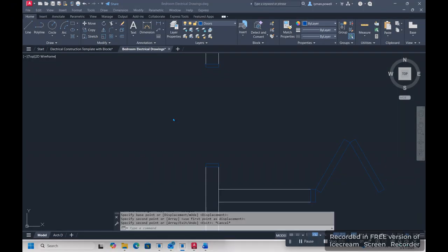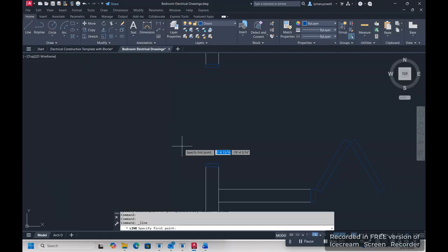So we're going to make us a right-hand door. That means the hinges will be on the right side as you're looking at it to go in. And we're just going to do a line from here, and this should be again a 30-inch door. So we're going to draw a line 30 inches, and you can just type in 30 inches. Again, it needs to be on the horizontal plane. So our door should be all the way open as we look at it. So we want a horizontal plane, type in 30.